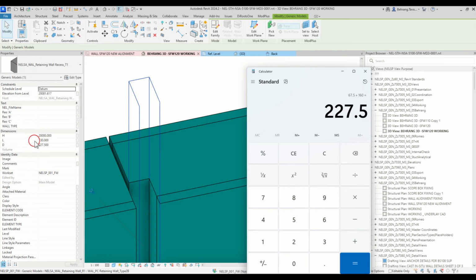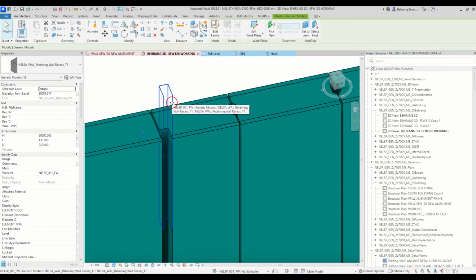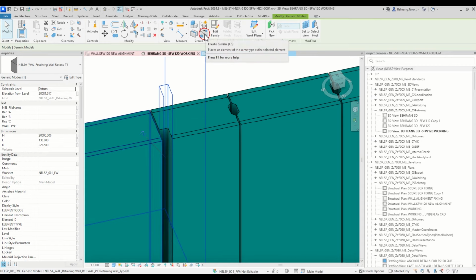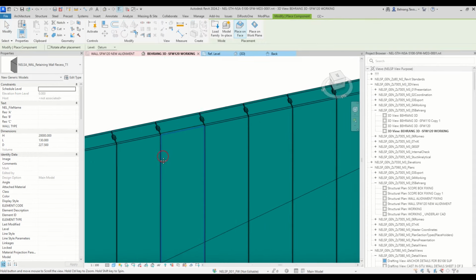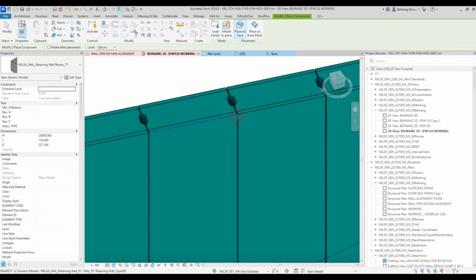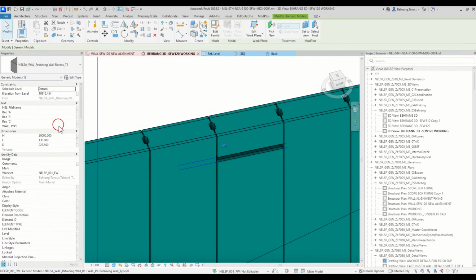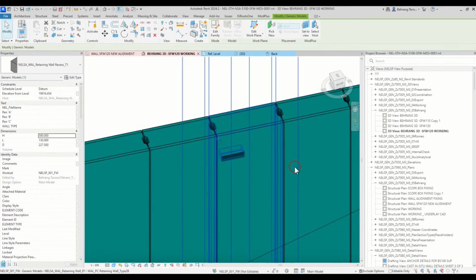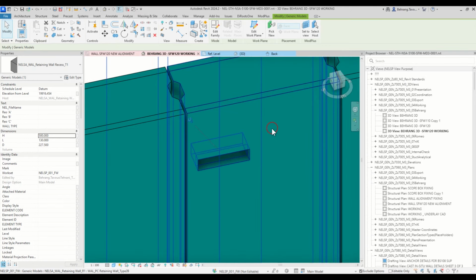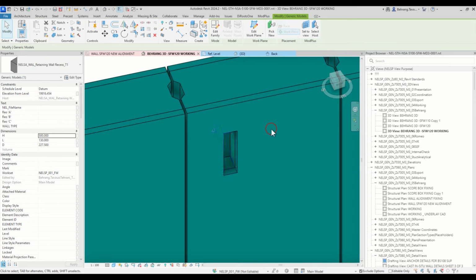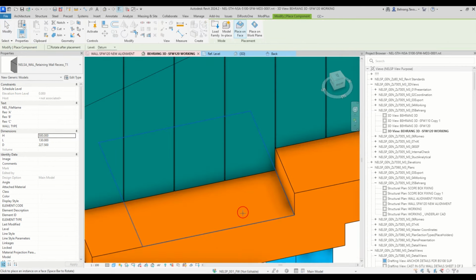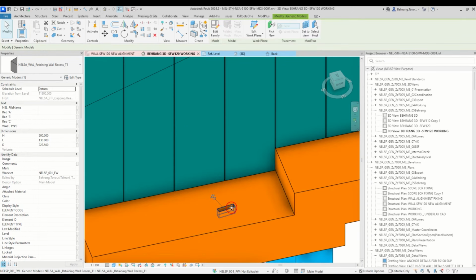Okay, and that parameter is here L, but we did it as a W. Width or L doesn't matter too much. But H is also the same thing. So let's click on this one and just type in CS for create similar, or you can just use this one, create similar. And let's say that we want to have that recess also somewhere on this panel. So I'm just hitting here, and by default let's have this one, for example, 500. So just having something smaller. Whenever you hit the space, it will also rotate. Okay, you can even create the same recess on this footing. So simple as that. You can create it everywhere you want.